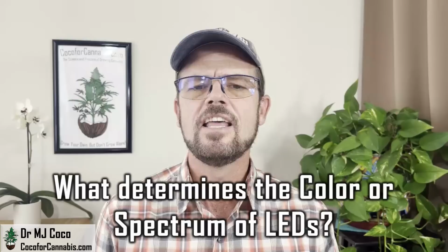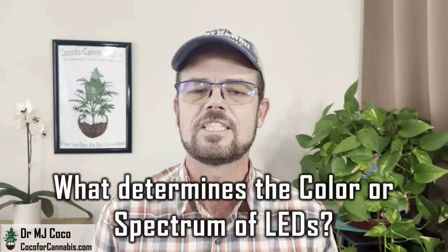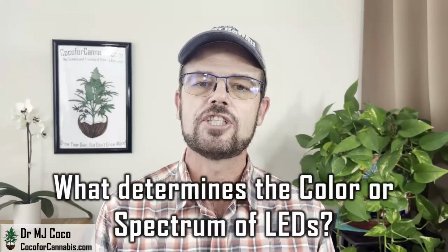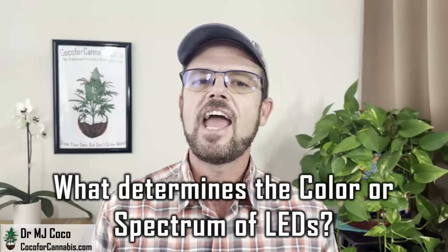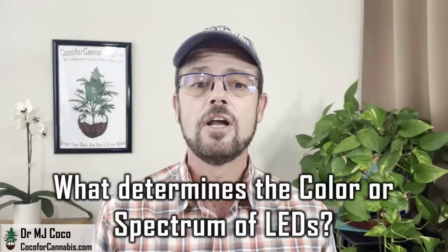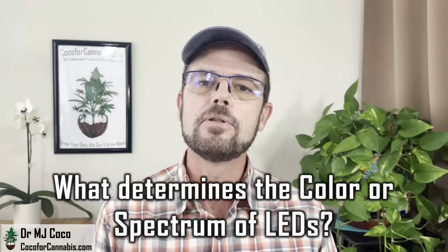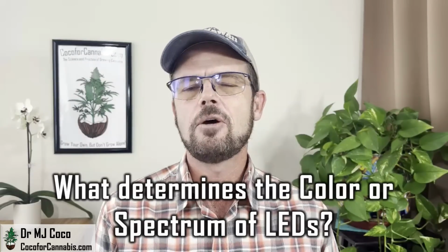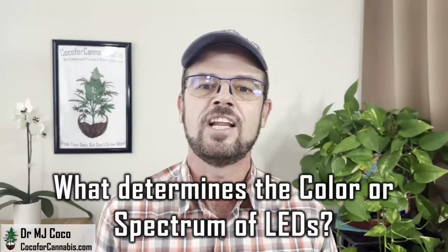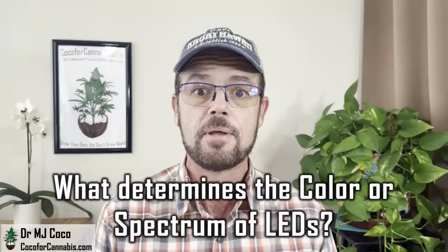As I just explained, the semiconductor in an LED creates photons as electrons drop to lower orbits. If the drop in orbital energy is small, then the photon will have little energy. It'll be a long wavelength, and the light will be red or far red. If the drop in orbital energy is larger, then the photon will have more energy and a shorter wavelength. The light can be blue or even ultraviolet. So it's all about how far the electrons are forced to drop as they cross the p-n junction in a semiconductor. In theoretical physics, this distance is called the forbidden gap.